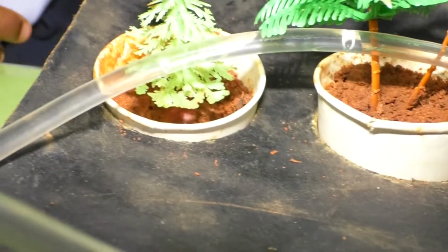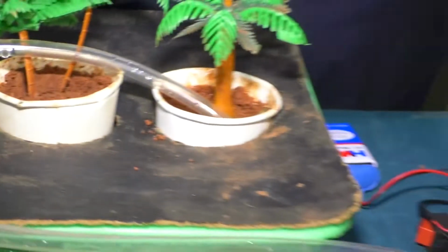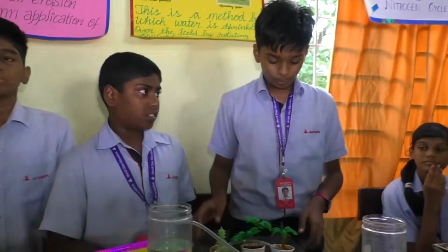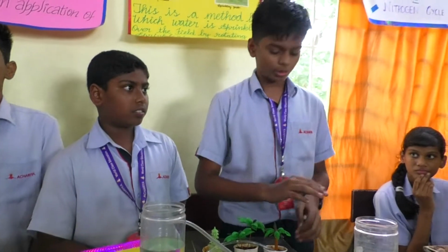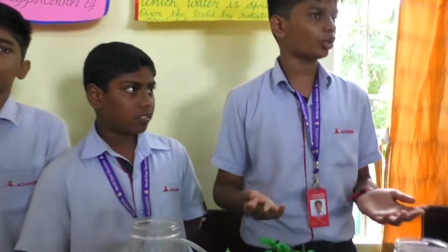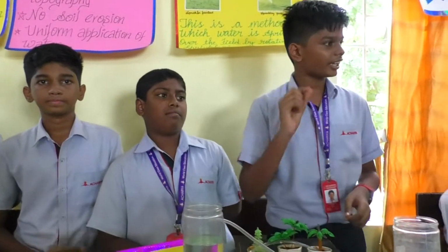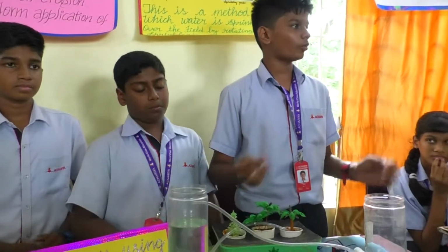Thank you. Now I will say some advantages of this drip system. Low water loss, efficiency up to 80%. By using this method, there will be no soil erosion. This method is suitable for any topography. Better seed germination, aeration of root zone and uniform application of water.